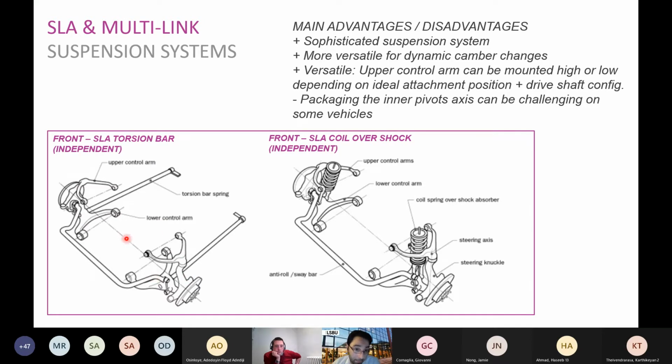In this system here on the left, you've got these torsion spring bars. So those are connected to your vehicle. And again, as you get twisting action occurring as you go over bumps and little hurdles, these torsion bars will twist back to a kind of home position. So very effective way of getting suspension back to home positions.